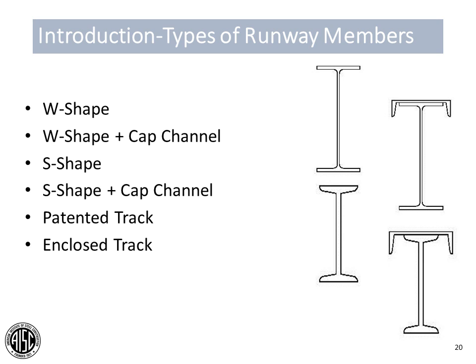Standard or S shapes are also a very good system. These do provide a narrower and thicker bottom flange, which helps with the resistance to local bending effects. However, due to the sloped top flange surface, you want to make sure that this is specified to your crane supplier early on in the project so that the proper wheels or end trucks can be specified and provided for your system.